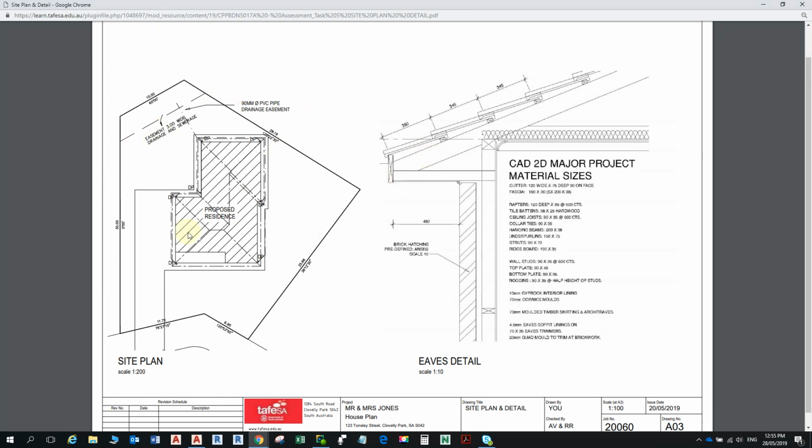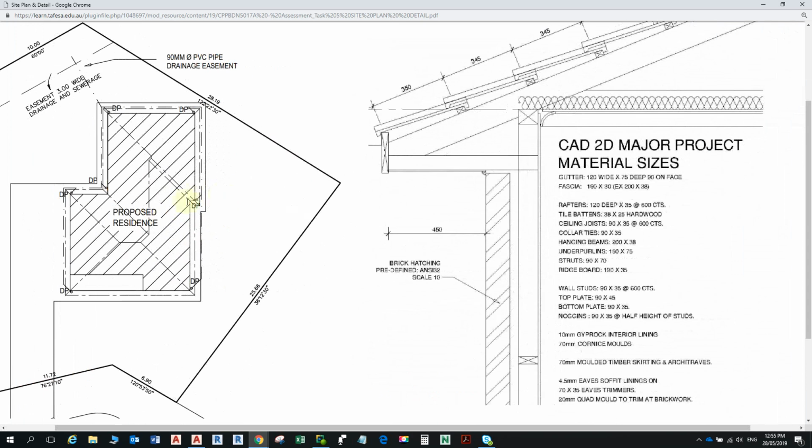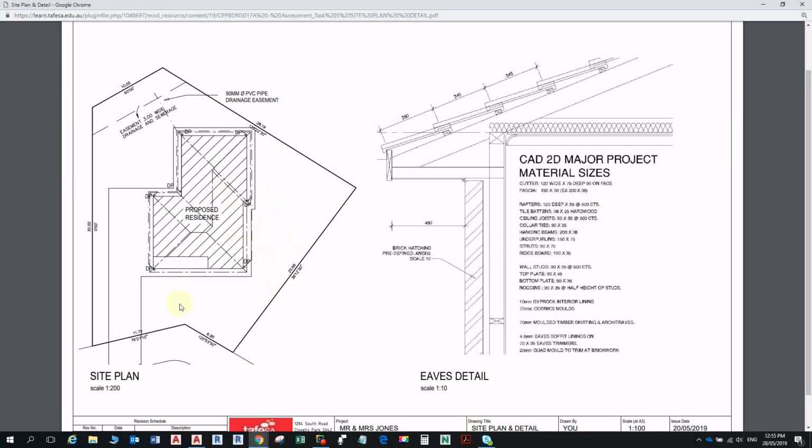What I added in here is the drainage plan, or the down pipes, that text, the hatching, and the proposed residence. Actually the roof plan shouldn't even be on there, I should turn that off. I also added the driveway, and that's all I've done. So basically, I'm using their drawing as a backdrop behind mine, and I'm just adding bits to it.